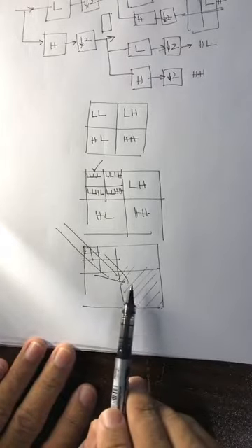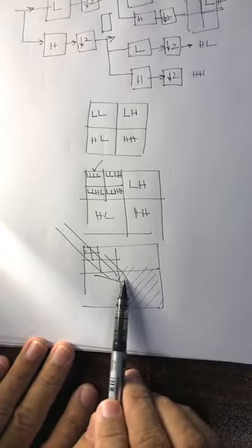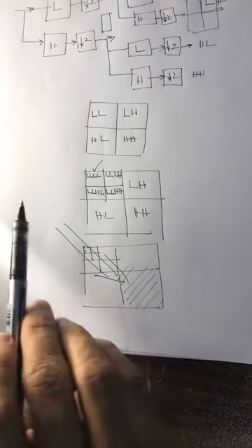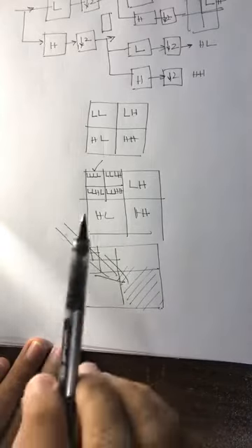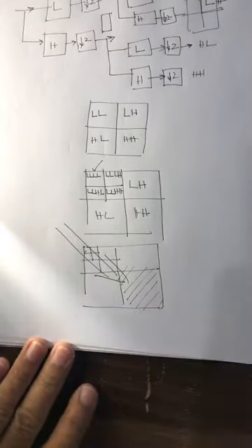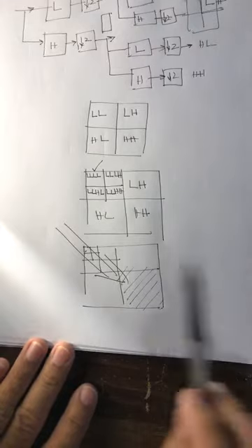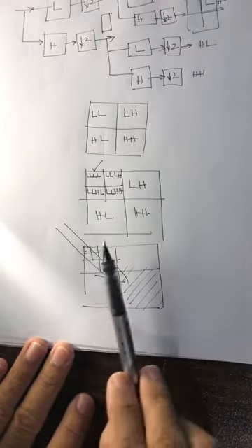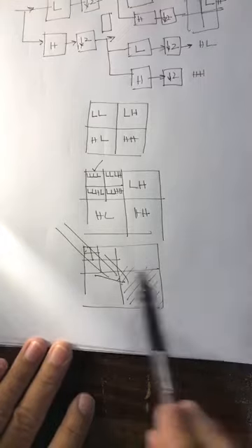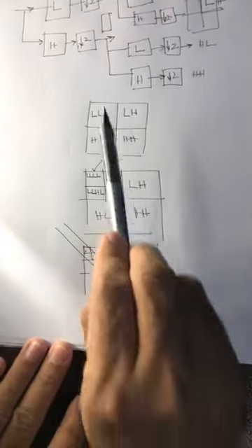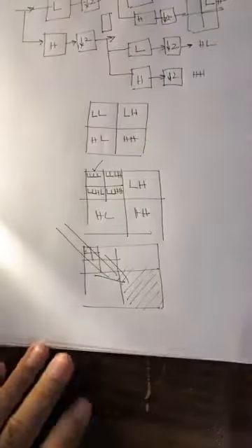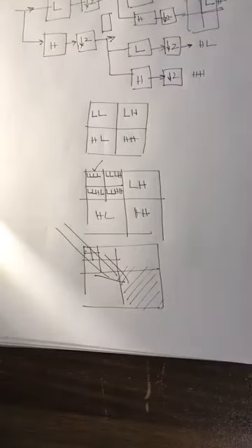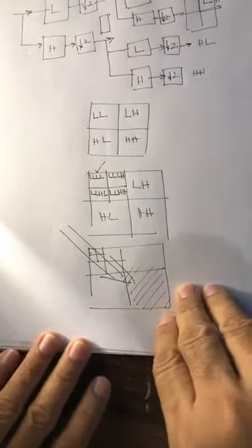So you can reduce an image by 10 times or 20 times because of first passing this image through a series of decimation steps. And once you are reconstructing, you go through an inverse process of interpolation. So from here you go here, from here you go here, from here you go here. You do decimation and you do interpolation in image compression as well. So decimation and interpolation are two very, very important operations.